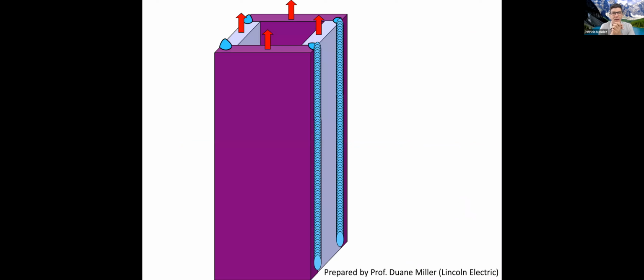This is an interesting one. In Japan, the anti-seismic columns tend to be these kind of closed box sections, right? So there's going to be tension or compression on these types of columns. What size should we make this weld? Can anybody make a suggestion? So the loads, this column C is tension and compression. What size would I give to these beads? Something you can think is, what is the nominal load that these beads see under tension or compression? Anybody?